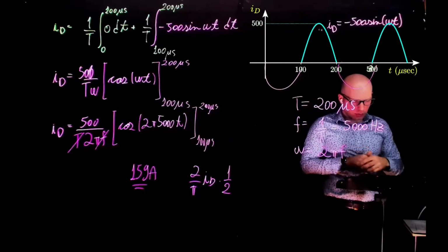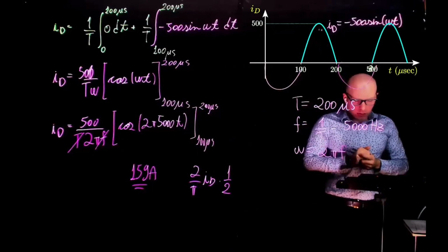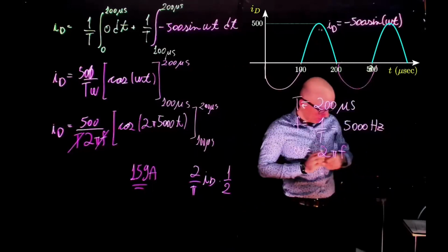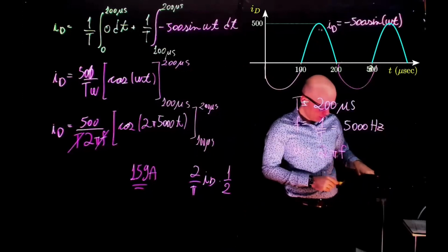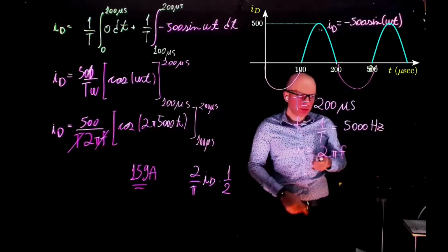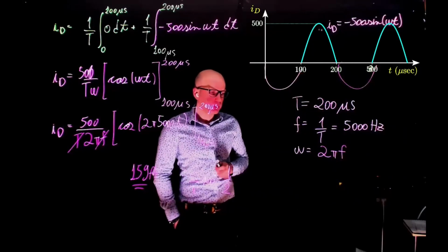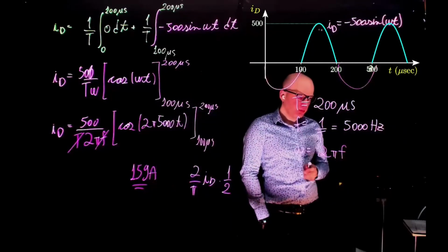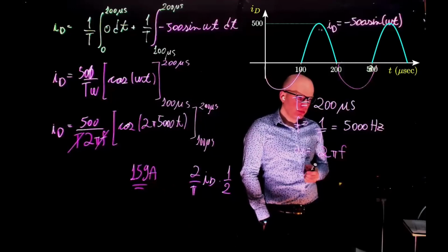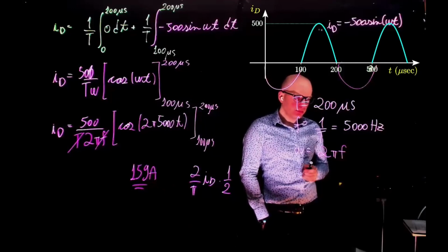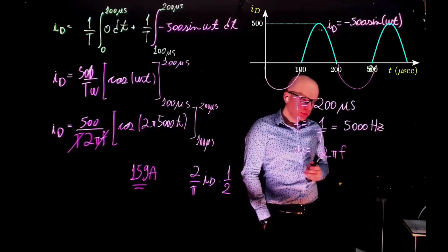I have a question. So generally speaking, are you saying that technically the final answer should be ID over pi? Yes. And when you're looking at full wave rectification, you'll have 2 over pi times ID as your final answer. Correct.